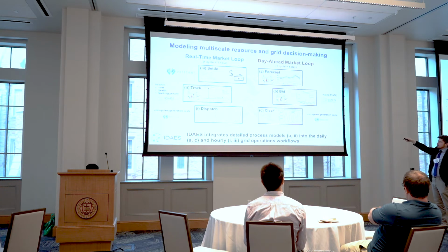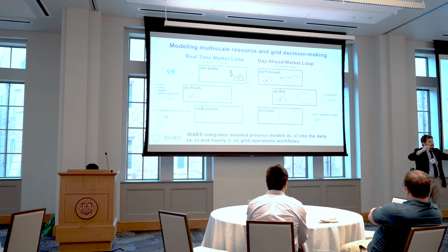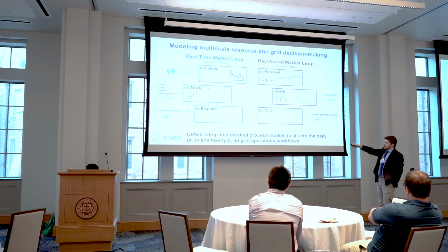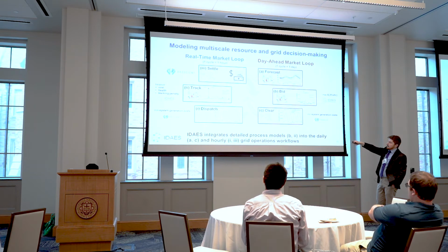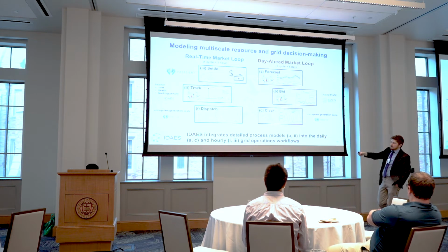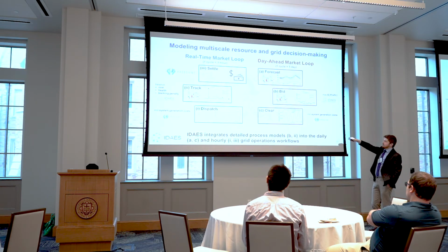Prescient takes all the data from every power plant in a region, and it's going to then determine the optimal schedule for the next couple of days. That then generates a dispatch signal, which then gets passed to our detailed process model, and then we can solve a sometimes nonlinear model predictive control tracking problem and say how would the system and maybe its storage be exercised in a way to track these grid signals, and then money drives everything, calculating how much the resource would make.